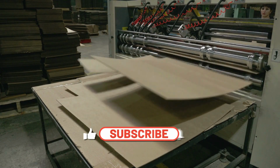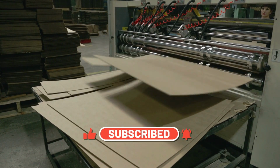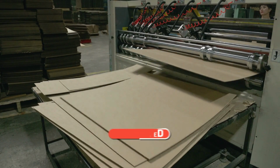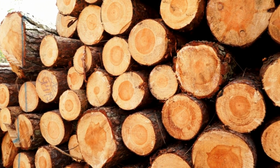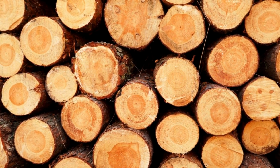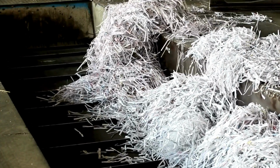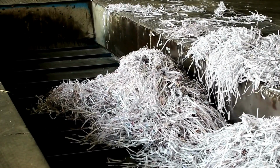In a factory, paper production involves a streamlined and large-scale process using advanced machinery. The first step is raw material preparation. Wood logs are transported to the factory and debarked, then chopped into small wood chips. Recycled paper is also used. Collected paper is sorted, cleaned to remove contaminants, and shredded.